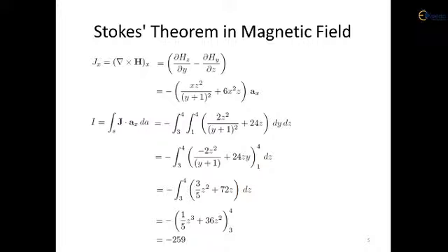Now we concentrate on the part B of this problem statement here. In the part B of the problem statement, we have been asked to find out the total amount of current flowing through the system here, where we have to carry out a closed line integral. So just recall back, in the beginning I have already shown you the mathematical expression as per the Stokes theorem here.